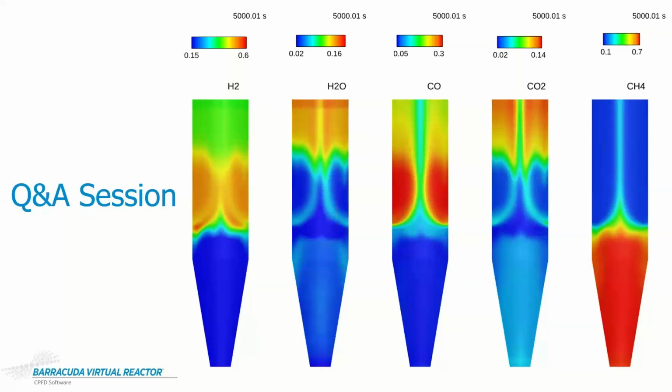You had mentioned baffles inside the furnace. Here's another question: can you simulate thin-walled structures and internals? Yes, so Barracuda does have a lot of capability in terms of being able to simulate internals using baffles. For these types of internals, usually they're very thin walls, so being able to capture them with a computational grid requires a lot of computational energy. And so baffles are useful because they exist on a subgrid level, so they don't actually need to be gridded.